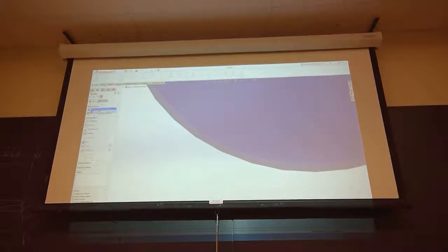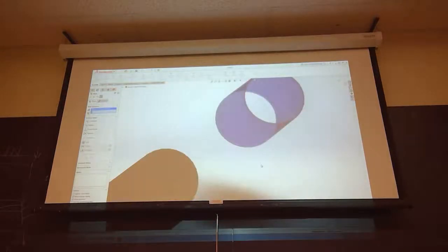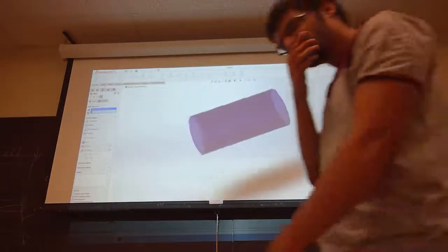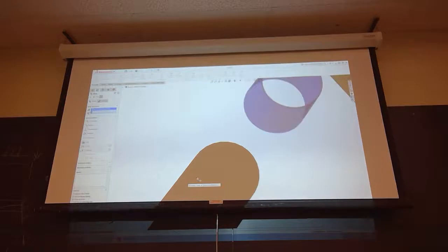Actually, it shouldn't be because I made all these parts. So it should say face, add coupler to 1. Okay, if it says edge, that means you did it wrong. Clear your selections, which you do by right-clicking, pressing clear selections, and then select it again, okay? So once you have that, make sure it says face, okay? Now you're gonna go ahead and rotate your component so you can see this side of the...